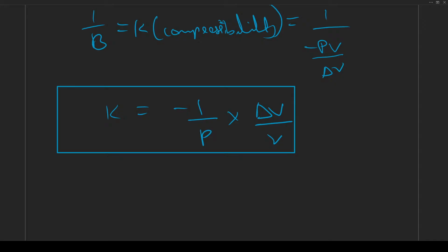The elastic modulus, Y equals FL by A delta L. The name of the modulus is Young's modulus. The state of matter is solid. Shearing: the type of stress is shearing stress, which is sigma s, equal to F by A.